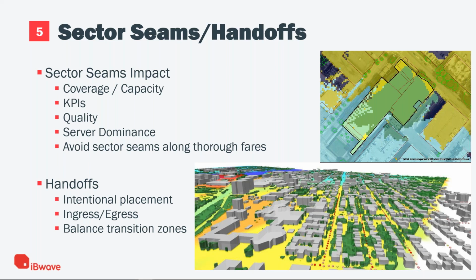But make sure that those sectors have a balanced approach across your design, because it definitely will impact the call quality and throughput. You may be providing a small cell at a location that is going to provide offload from the macro network, but because you need to consider how much coverage is coming from that macro design, it could ultimately create a SINR or SNIR issue that will impact the call quality or the throughput quality because of the amount of RF energy in that area.